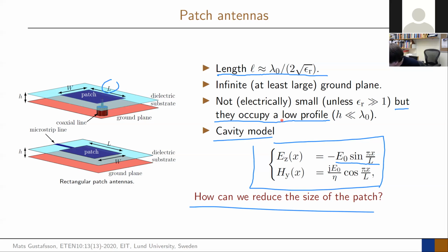It means that if you go to the center of this patch, along a line here, along that line, the electric field here is 0. Because that's in the center of it. And if you remember of your patch antenna, if you put the feed in the center, it doesn't really work. And that is this electric field that is 0. Your radiation resistance goes to 0 at this center point. So you cannot feed it in the center.